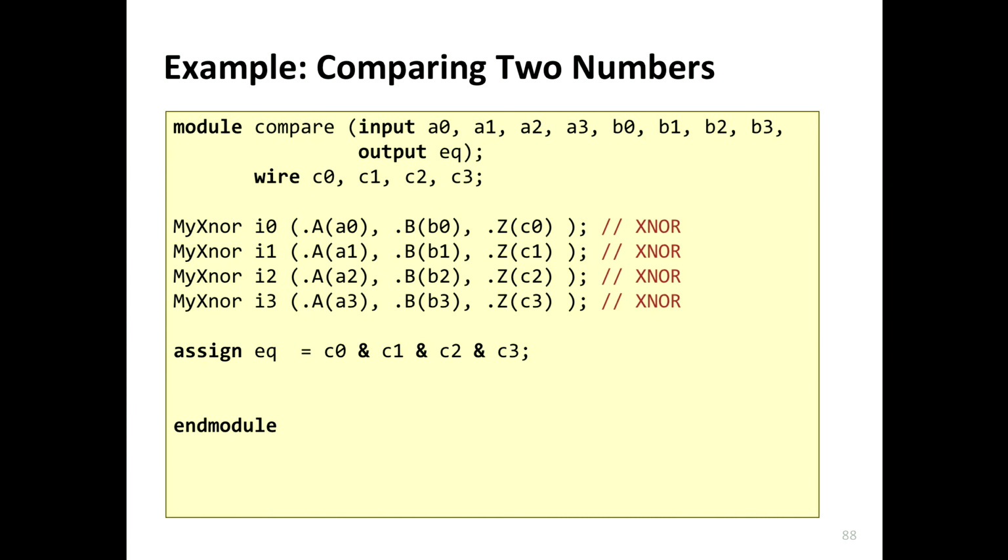Because sometimes you can restrict it and say, okay, I don't have 4 input ANDs, and typically you will not get this circuitry. Because of how the hardware is realized, it's much easier to reuse 2 input ANDs. So you are typically restricted with this. But otherwise, if you are not restricted and you are doing circuitry with schematics, you just simply don't care.